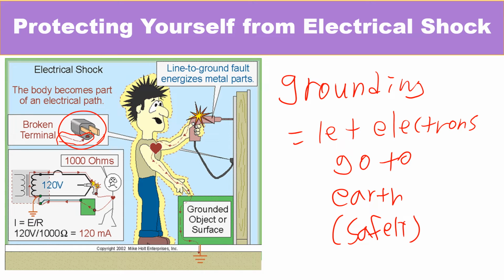So theoretically, imagine this is an electron, it should go through the device, let the device do the work, so potential energy does the work, and it should go back with the help of this terminal over here. But if that terminal is broken, then instead of going through the plug-in, it can go through your body and then ground through your shoes, or if you're touching any other object, it may go there too. So your body is now a circuit. You're going to have an electric shock.